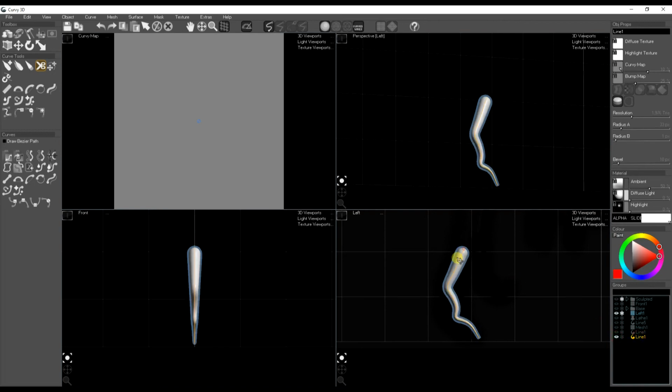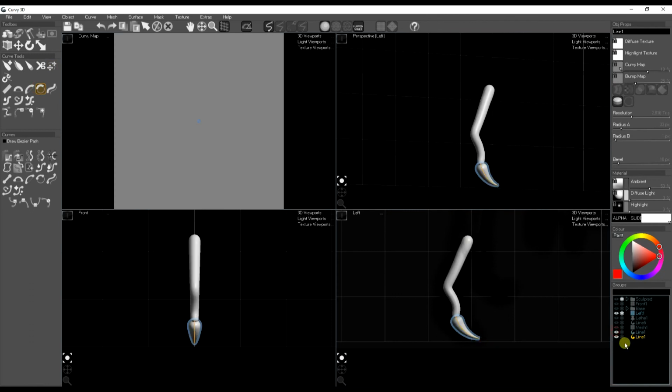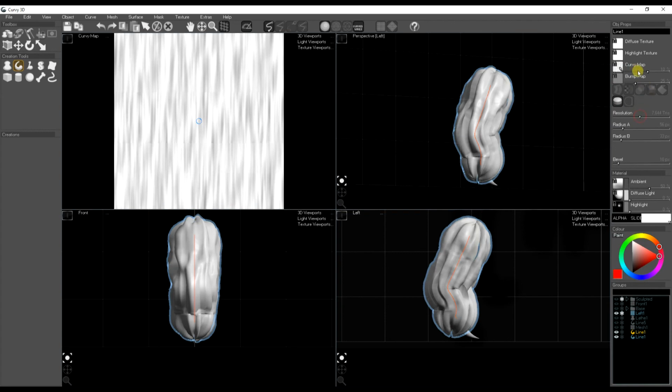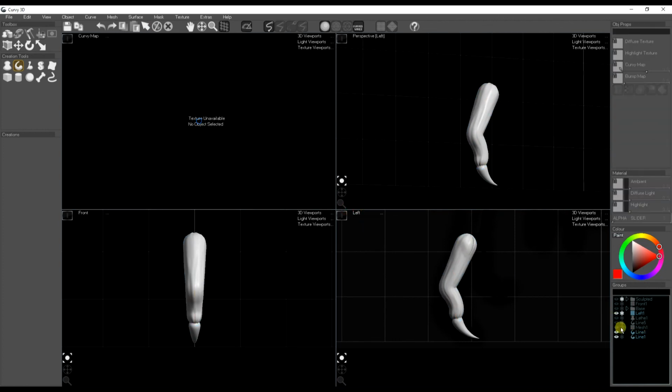separate. To get the claw cut off, I need to use several cuts, because it always cuts off the shorter part of the curve. So I need to trim it off several times until I get the claw separate, and then I can adjust the radius to make that look more natural, and add again the noise to the skin to make it look rougher. Again, we increase the resolution and decrease the effect of the Curvy map to make that more delicate. And that's his fingers done.